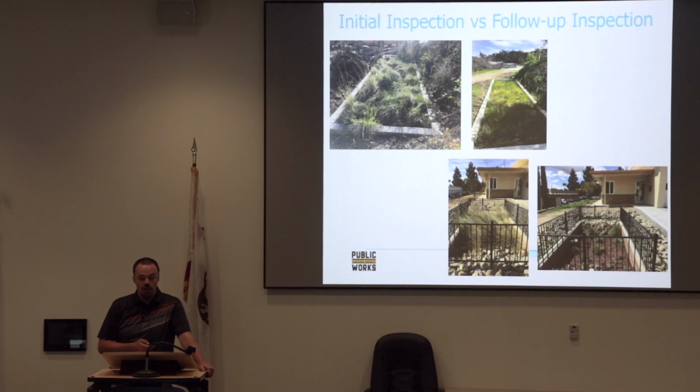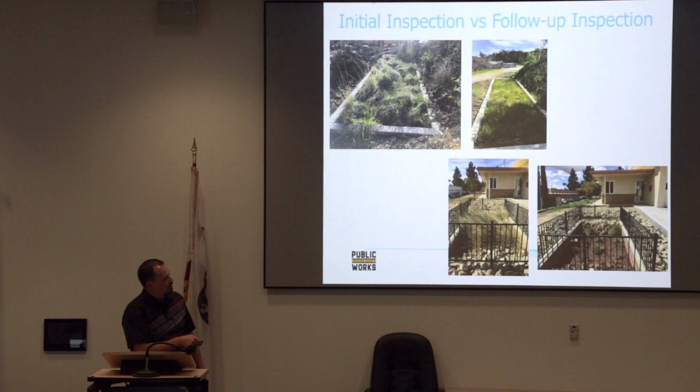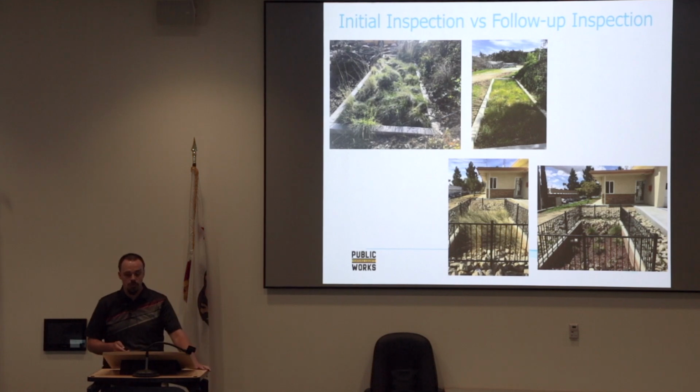The second one, we have overgrown vegetation. You can see in the bottom right picture, here's the inlet pipe, for all the water to come in and start filtering through. And it was clogged from this vegetation, so they trimmed it down. In areas where the vegetation had died or just hadn't taken, we did allow them to do some mulch until that other vegetation did pop through.